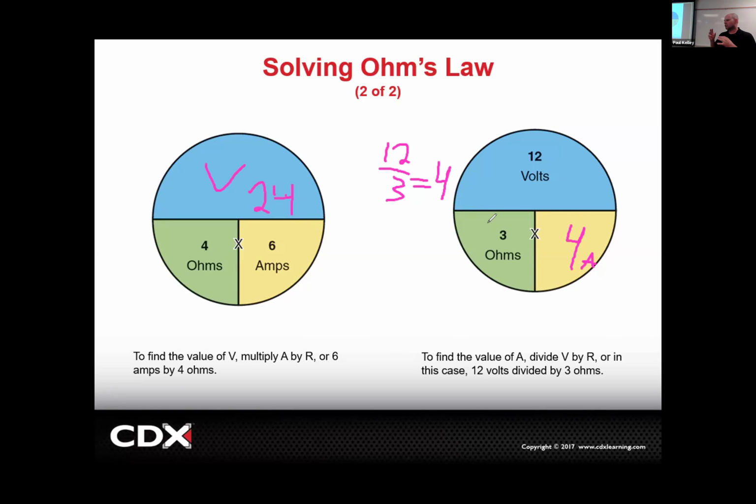So what we would need to know is how much resistance there is going to be in that filament when it's glowing red hot. And then you could get the exact amps, right? So we did a calculation based on the cold resistance, whereas we need to do it with the hot resistance. And that's why when we do our experiments, you may notice they're a little off. You'd be like, huh, did I just break Ohm's law? No, not really. There's variation in temperature.